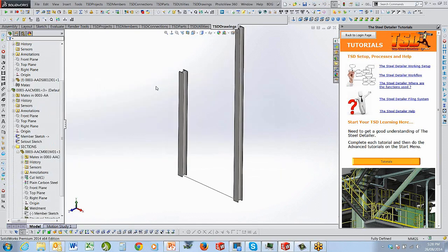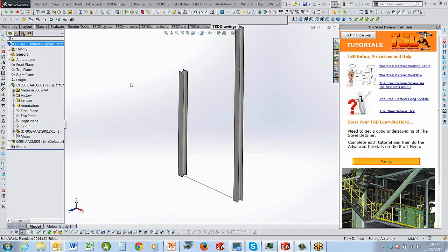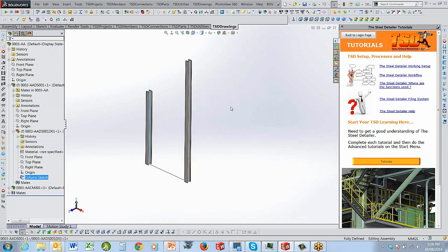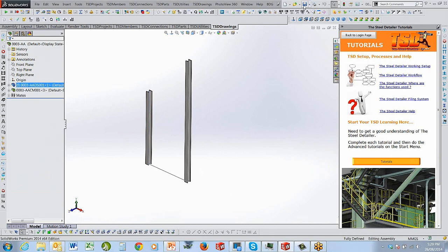That's how you create welded frames, okay? Now, the driving sketch that I have in here obviously can be a myriad of things. It can be a grid for a building. It can be a complete frame. I've got some frames here to show you so that you can see how they're done.